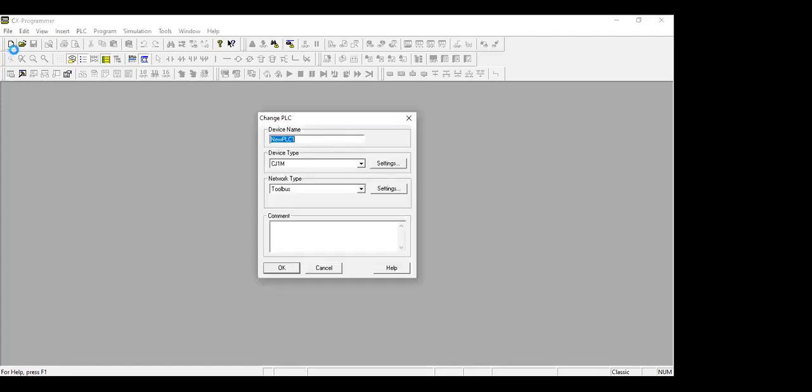All right, so we press on the file and open. And then the thing that we have to change in this is this. We have to find the PLC that we are going to be using. The one that we have in the lab is CP1H. The default that comes up is CJ1M. We used to have CPM1A and CPM1.